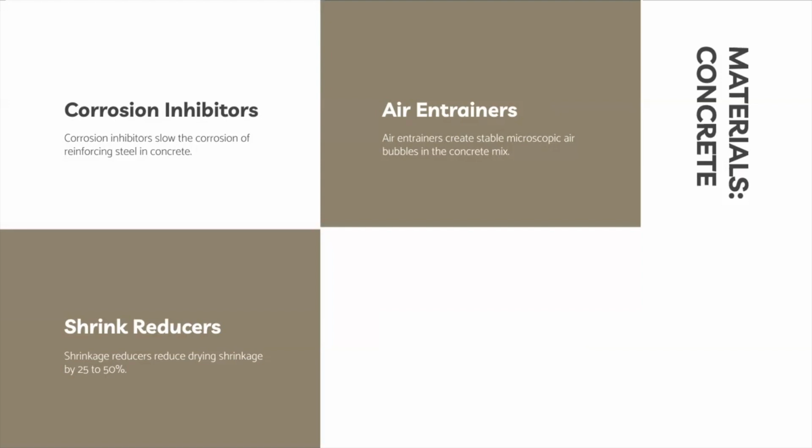Air entrainers introduce stable microscopic air bubbles into the concrete mix, reducing its strength but enhancing durability in freeze thaw environments. These air pockets accommodate water expansion during freezing, mitigating internal pressure and enhancing concrete's resistance to damage.